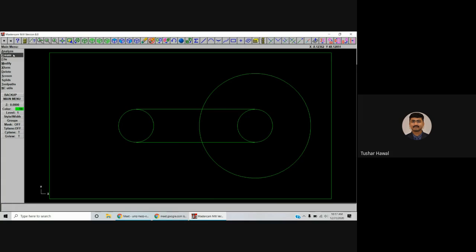Then I'll go to the create option. I'll create a line, a vertical line. For creating the vertical line, the first point I will give as 70 comma 0, because the y value I want is 0. So from the bottom side I'm going to start. I'll click on this line at the top. Okay, so it has taken the x coordinate as 0. This line I have created as a reference. When I offset this line by a distance of 62.5, I'll get the required line.